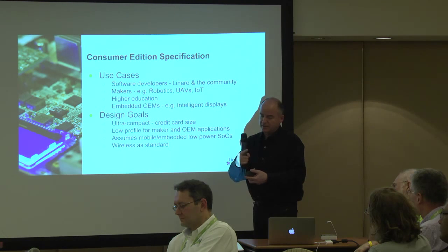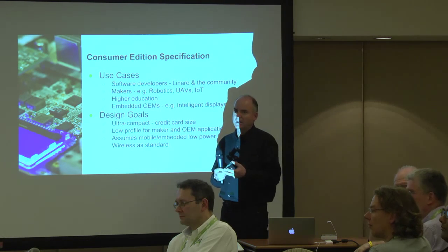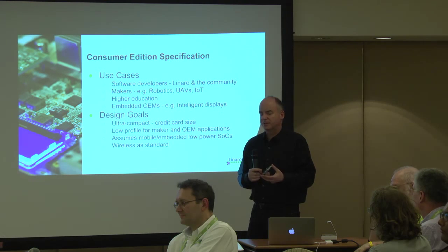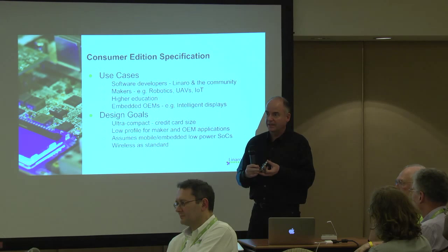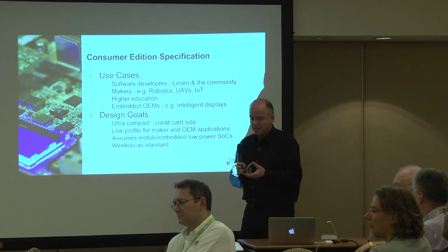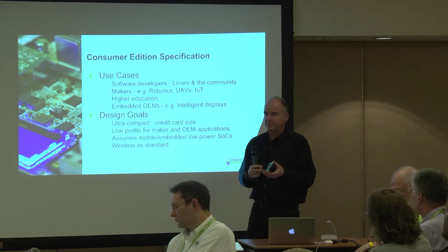So all of the connectors are just coming out nicely from either the front or the back. So there is no serial by default, in fact? There is. So the serial console, there are two options, right? The serial console comes out of UART 0 on this, and you can put a pin header or have a board that comes out to a nice FTDI connector. The other place the console comes out is on HDMI and USB input.